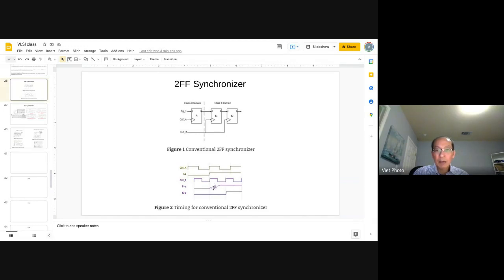The first clock captures it like this, and during this time the circuit will function abnormally, so we don't want it. The reason for the second flop is just to time it at the second clock, so it will be delayed by one more clock. That's all. So the question that I think you guys failed is the metastability, right?